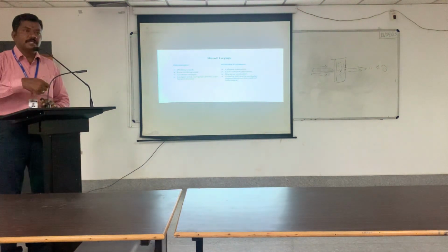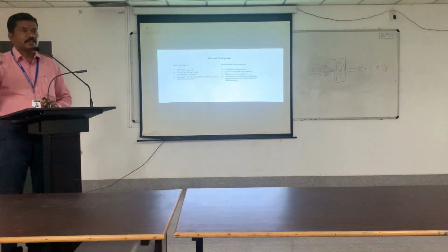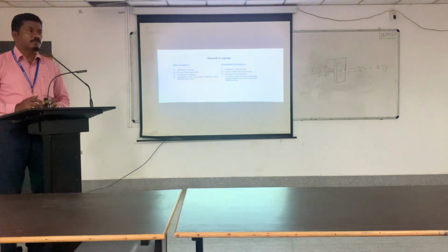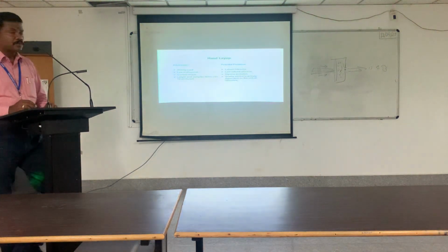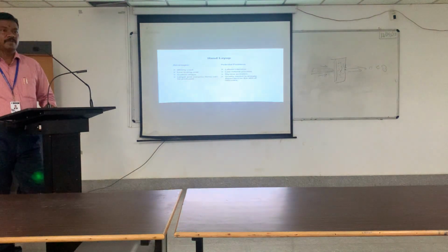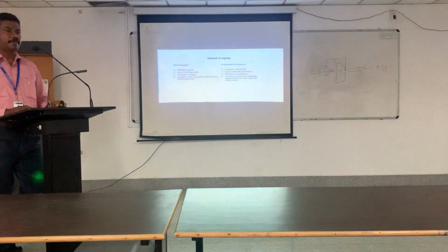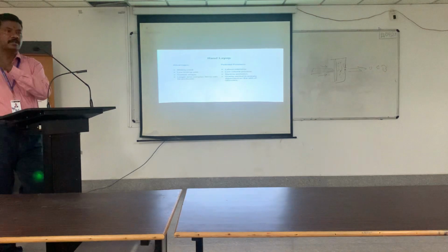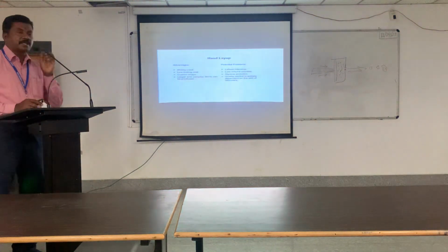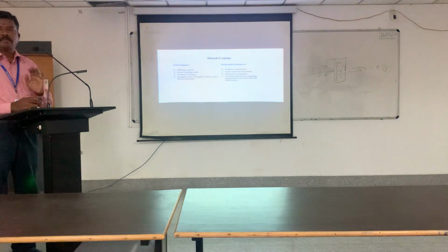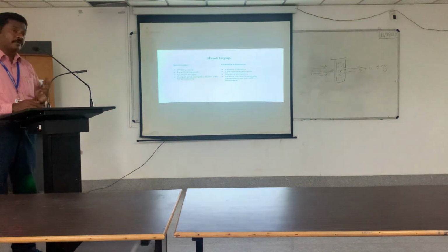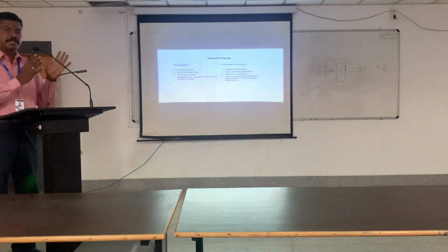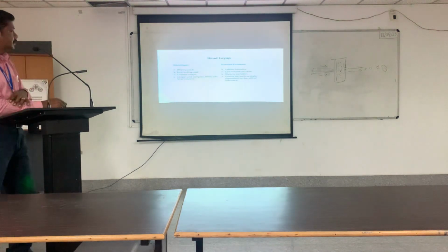So during rolling, initially for 10 pieces you will apply a certain amount of pressure, then due to the fatigue of the human, towards the end you will not concentrate as much as before. So consistency across all the plates will not be there in the hand layup method. But if it is machine operated, we can expect all 20 plates to have the same quality. Right? So inconsistency is the major drawback of hand layup. Even if you use the same labor, same material, same environmental conditions, you cannot expect the same property in all the products. Okay.